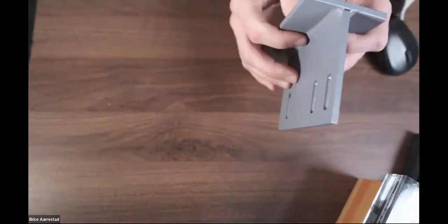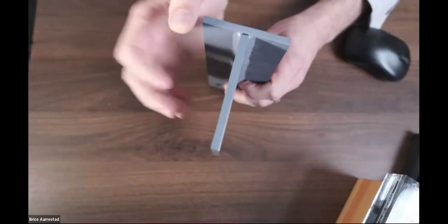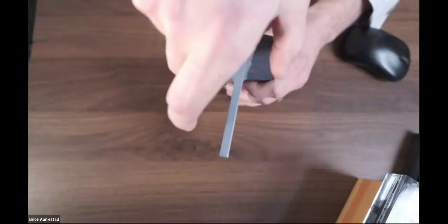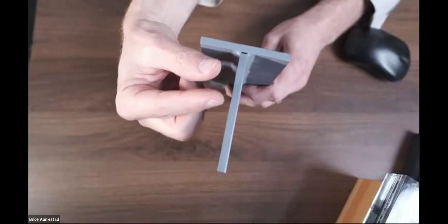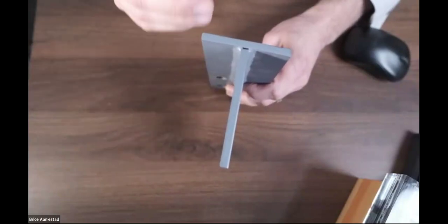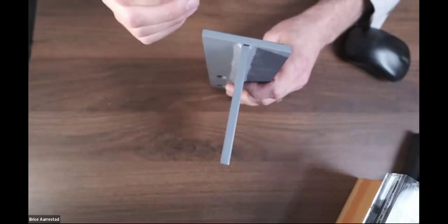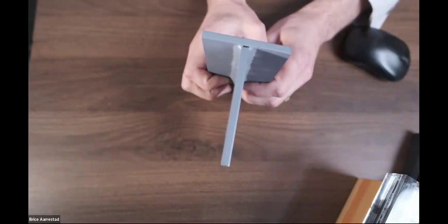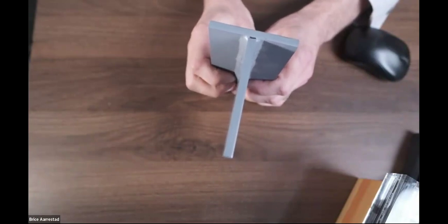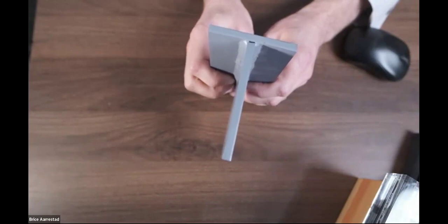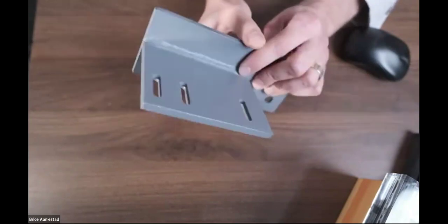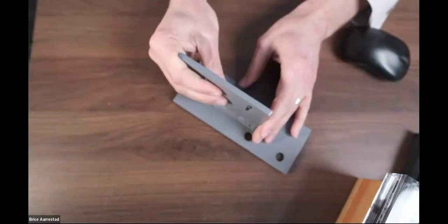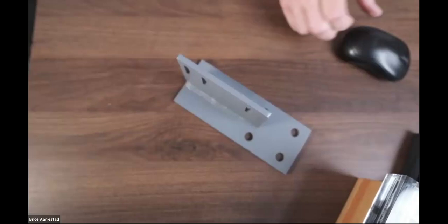In a typical arrangement, this would be, let's say, at the head, and the timber would slide in here. We would route a receiver for that, so it would slide in here. There would be a gap that's allowing for deflection between the structural member above and the curtain wall, so that any pressures that are being applied, be they a snow load or a live load on a floor, would not be transferring that deflection into the curtain wall, because we wouldn't like the glass to break. That's usually a bad thing. So that's one of the anchors that we use pretty frequently.